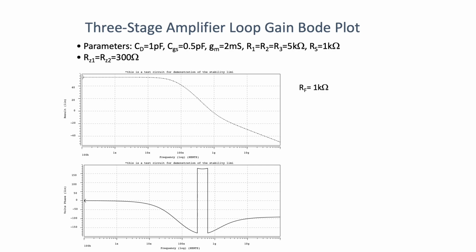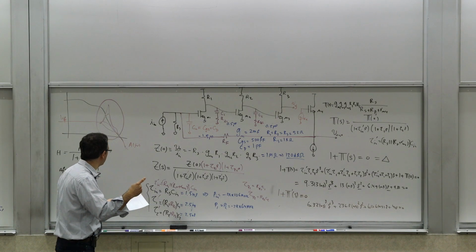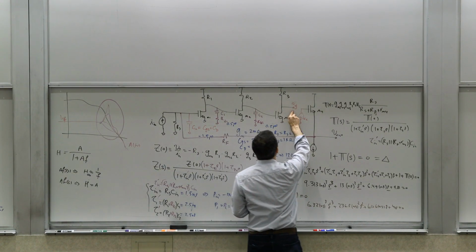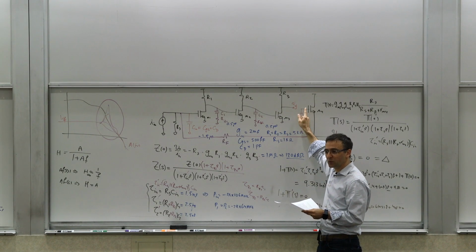So there's nothing extraordinary happening. But you can see that at those 2 points where it's flipping, you have a forward gain, a loop gain magnitude greater than 1, because you're above 0 dB in both cases. So you have a loop where the return is going to be larger. When you break the loop, what comes back is going to be greater than what went in.